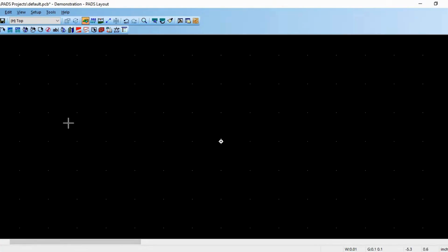Now I will set the size. This is a bigger PCB, and I don't require such a big PCB. I require a very small PCB from this. So I will take a board outline. Here in this toolbar, you have the board outline cutout button. Just press it. From the 0 point, you start it. Just left click on your mouse and a pin starts from here. I will go here up to this point, then I will turn to the right, because I'm taking a square PCB.